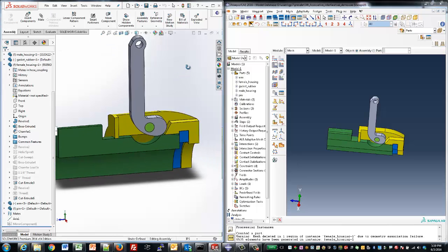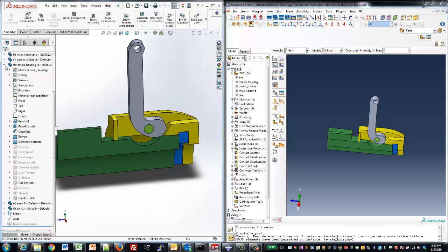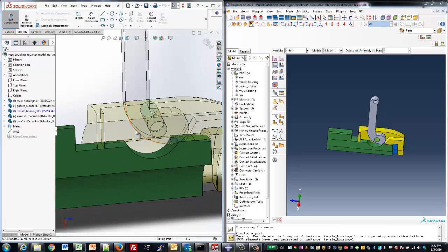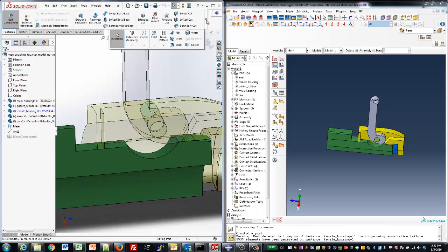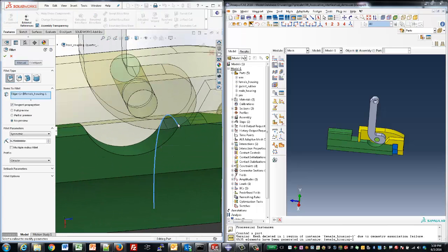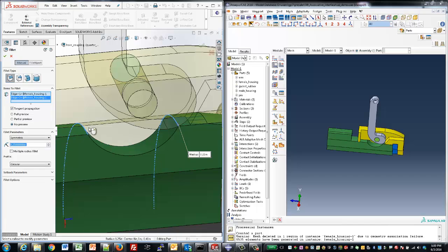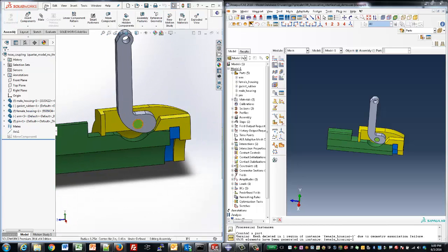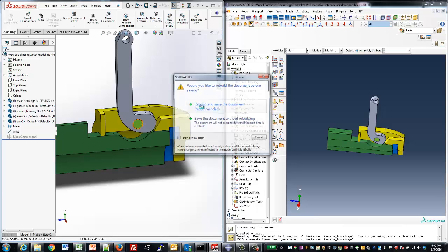plastic strain. We'll move right back over to SolidWorks and make the geometry modifications using the Fillet tool right within SolidWorks. Creating a fillet on those sharp corners is just a couple of clicks, and we'll go ahead and enter a dimension there. And from here, all we want to do is dump the geometry back into Abaqus.